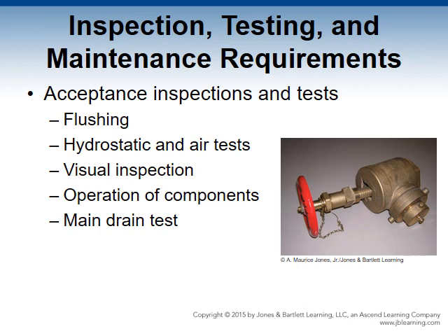Hydrostatic test for residential systems. For NFPA 13R sprinklers, the hydrostatic test pressure should be equal to the water pressure of the system source. If the system requires a fire department connection, the test must follow the requirements of NFPA 13.